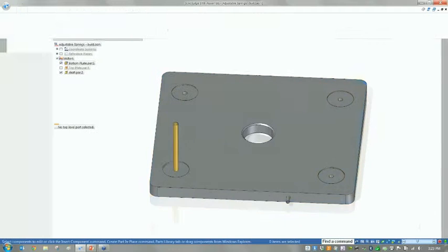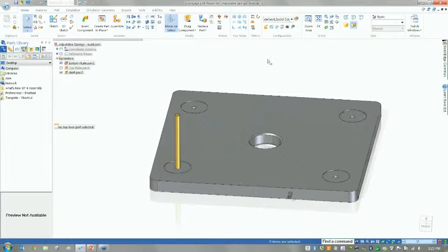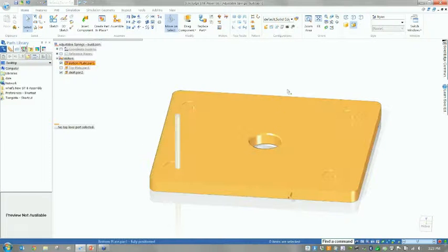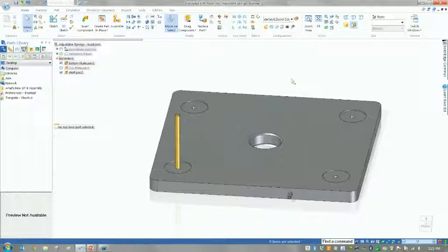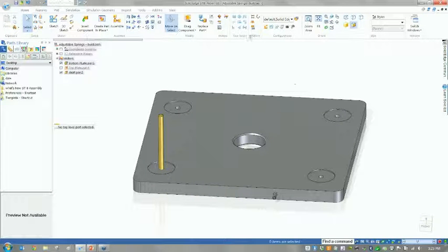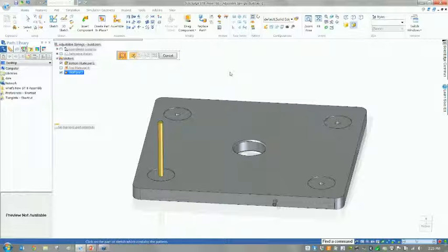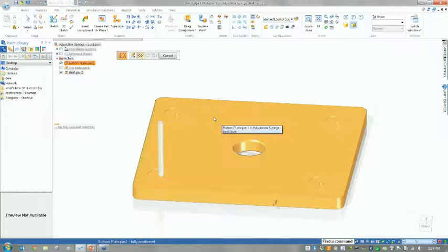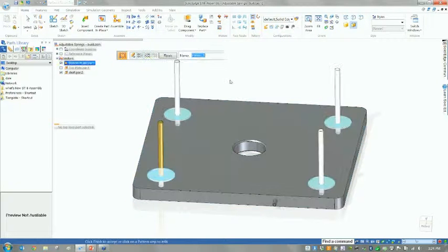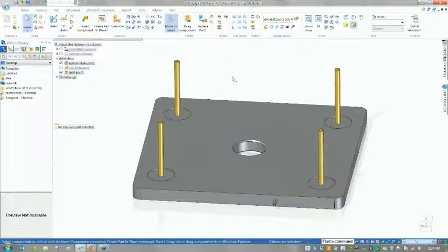At this point, I'll close and come back to my assembly. So this plate here could have been in IGES, it could have been in STEP, it could have been from anything. It could have been 3 or 4 holes put in at different times by different people. But now it's my pattern. So I just take my assembly pattern, and I'll say take piece, yes, and put it in this pattern, and it's going to go in all 4 of those holes just like that, where we couldn't have had that before.